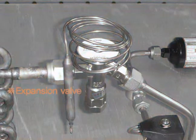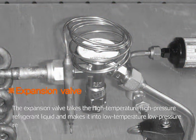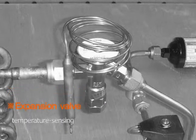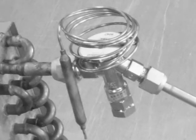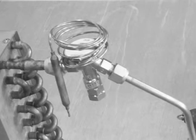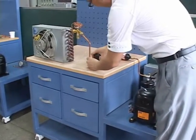This is the expansion valve. The expansion valve takes the high-temperature, high-pressure refrigerant liquid and makes it into low-temperature, low-pressure refrigerant through throttling. There are temperature sensing type, manual type, and capillary tube type expansion valves. The temperature sensing type is again classified into internal equal pressure line type and external equal pressure line type. Here, we use the external equal pressure line type. The piping of evaporator charge and expansion valve discharge will be completed.